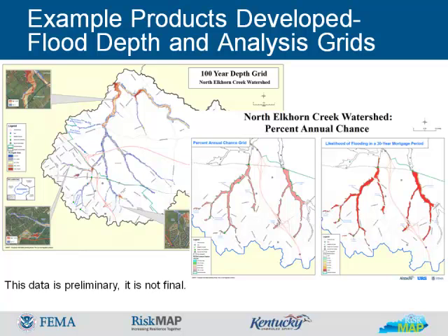The flood depth and analysis grids can also assist with enlisting the support of elected officials and local leaders by identifying areas of highest flood risk according to frequency and magnitude for possible mitigation actions, even if the action is to maintain open space. They can also help building officials, property owners, and developers understand the elevation requirements for specific sites according to local flood damage prevention ordinances and how those may change over time.